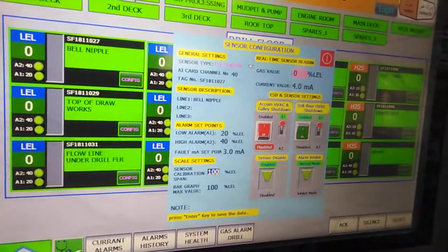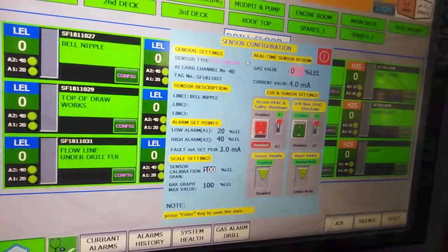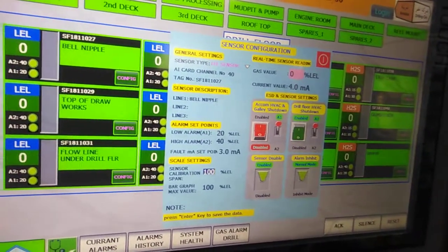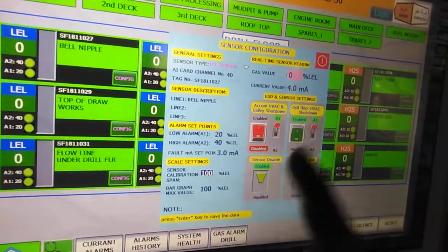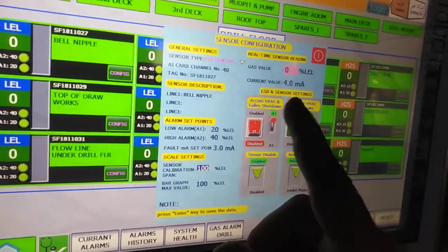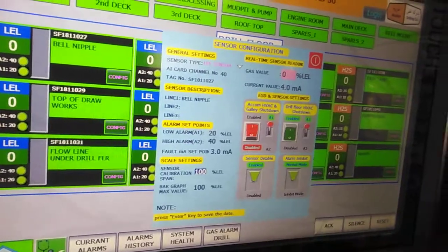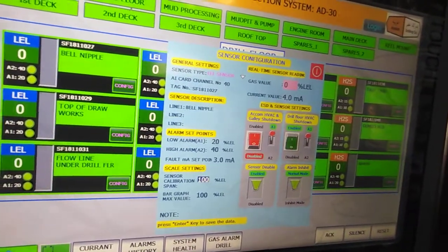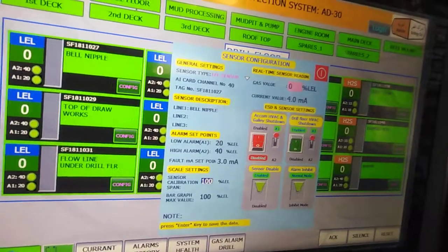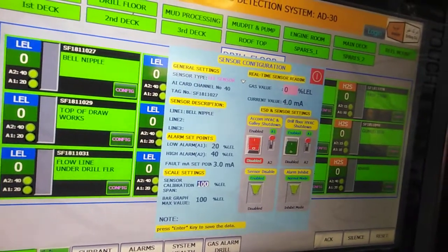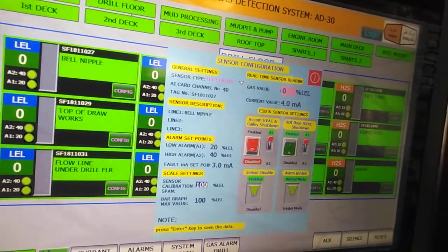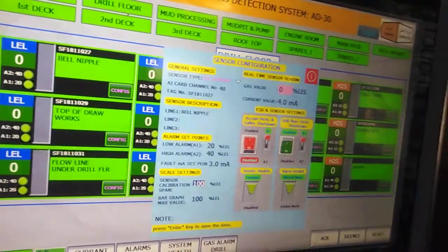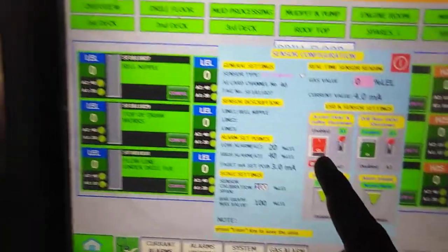When this gas is detected in the oil rig, we can automatically shut down the accommodation HVAC and galley equipment, in order to prevent fire smoke entering the accommodation area, reducing the oxygen level and causing suffocation. We can select either to enable or disable.